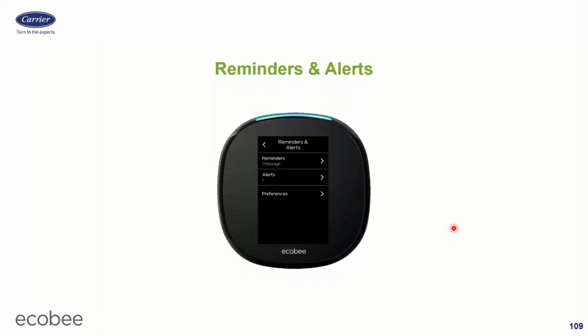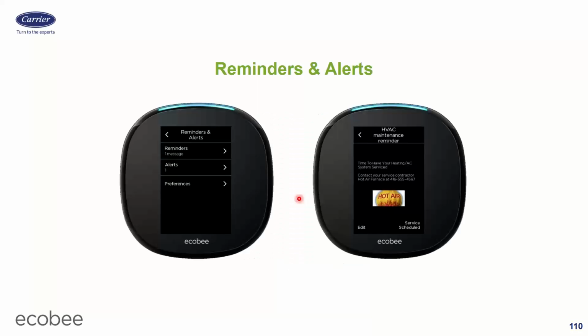When you go into the reminders and alerts tab, which is also kind of homeowner-ish, there's a couple settings in there that you probably want to change before they even use the stat. So there's 3 tabs on there. 2 of them are just read-only. You can read any reminders you have, dirty filter, change your UV bulb, etc. And you can read any alerts you have, temperatures out of set point range, whatever, right? The third one, preferences, is the one where you set all that stuff up. So that's what we're going to click on is preferences.